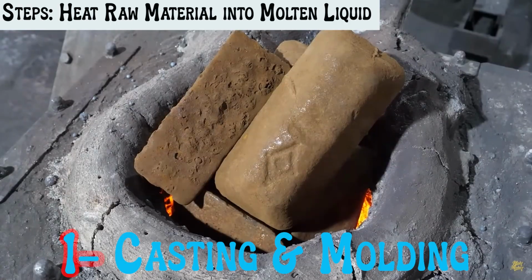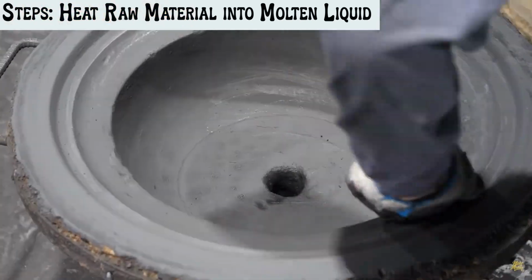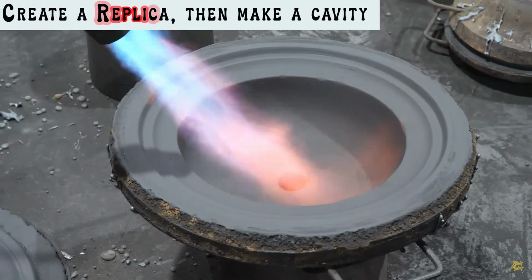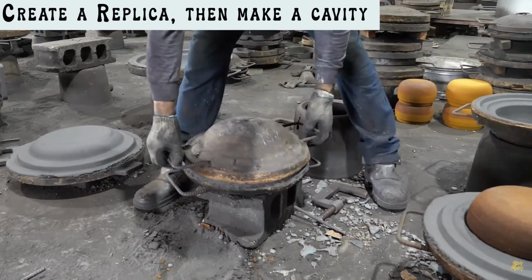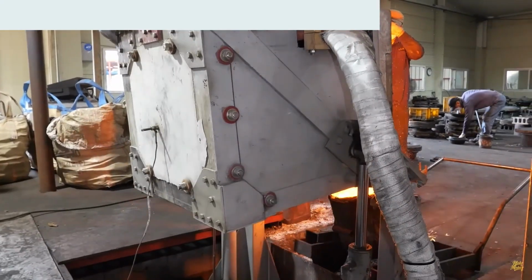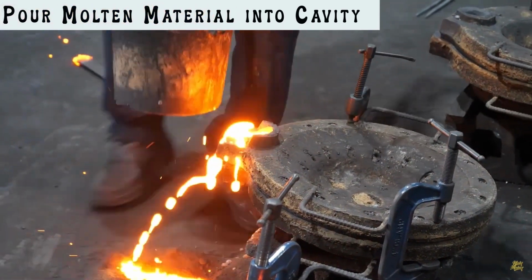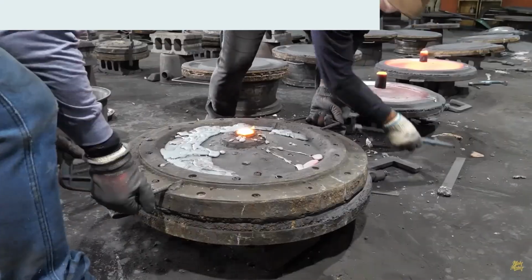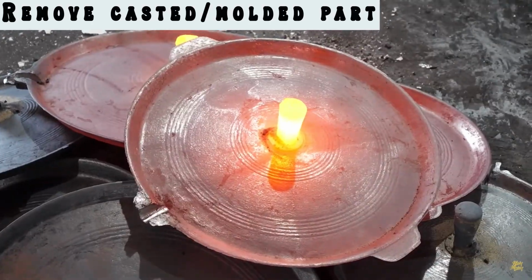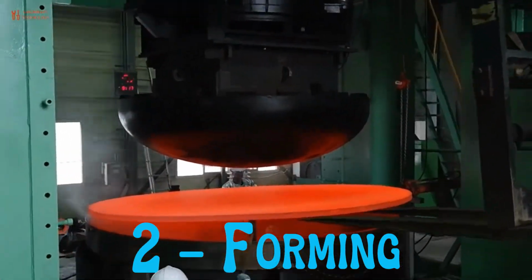The first one is casting and molding. Heat raw material into a molten liquid, create a replica of the part to be casted, and make a cavity. Pour the molten material into the cavity. Remove the casted or molded part and let it solidify.